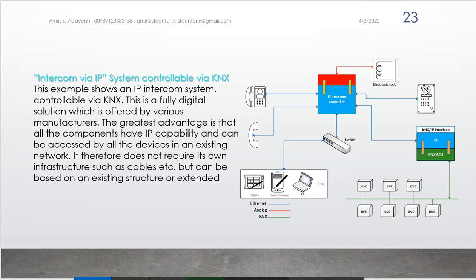So we have the SIP outdoor station and the SIP indoor station, or IP outdoor station and IP indoor station, and they communicate with each other. We connect them to the switch, and that's it, it's done. For example, the indoor and outdoor stations from the company 2N, or Akuvox, are SIP, so you can use them.